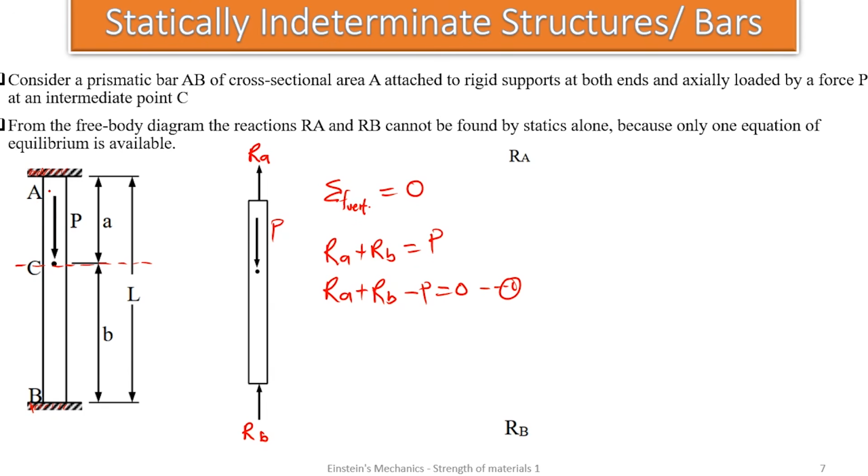That's how it works in this type of structure. Because it is fixed, there's no movement outside its scope. So if A is elongating, there will be a contraction in B. So at the end, the summation of the individual elongations will be 0.